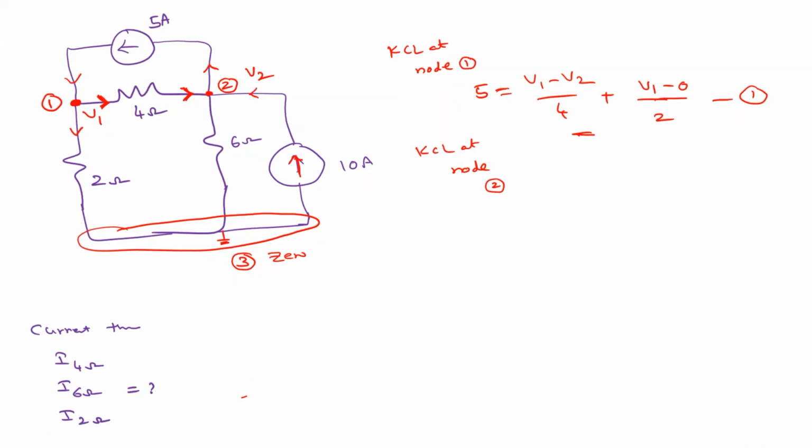Okay. So now there is some conflict here, right? When you are choosing this 4 ohm, you have already assigned the direction when you were assigning node 1. Either you use this same direction, or you can use your own direction. But when you're writing that, the current may be on the incoming side or the outgoing side, and we must take care of that. For your convenience, I assume the same direction, and this is the outgoing current.